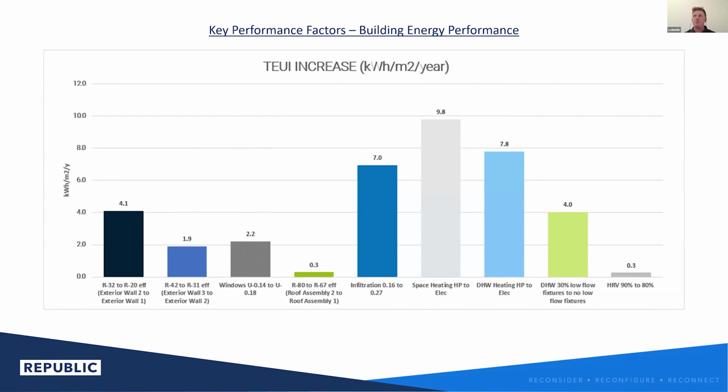So it's a fairly moderate target considering Passive House is 0.6. We found that we probably could have gone to an ACH target of 1.0 and still reaped some benefits from that. But there was a bit of hesitation to make sure that we weren't setting ourselves up for failure by being too aggressive.